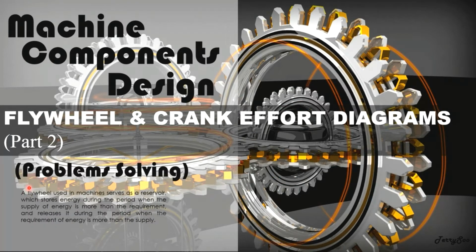Now we are moving on to problem solving. So this will be the first example. The turning moment diagram for a petrol engine is drawn to the following scales. For the turning moment, 1 millimeter is equivalent to 5 Newton meter, and for crank angle, 1 millimeter is equivalent to 1 degree.